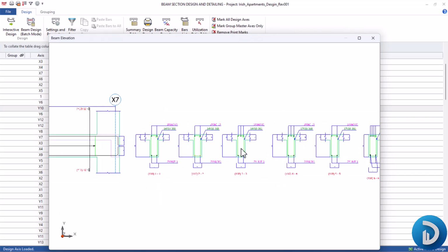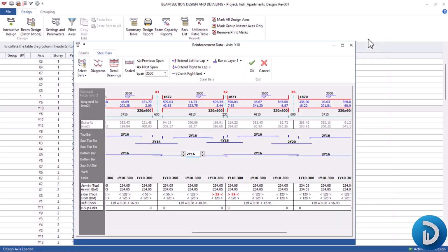So what some structural engineers can decide to do in this case, in order to minimize errors on site or errors due to detailing, is to select the maximum reinforcement at the top zone, then use this as a conventional reinforcement all across this top zone. The maximum at this top zone: we have 2Y16, we have 3Y16 here. Here is 2Y16, here is 4, which is the maximum.